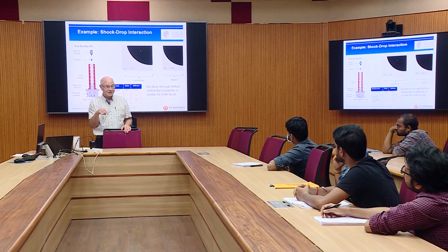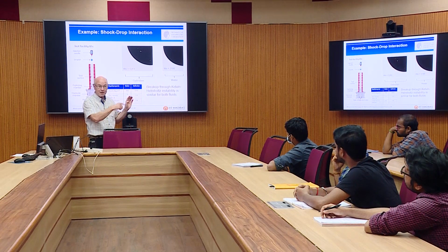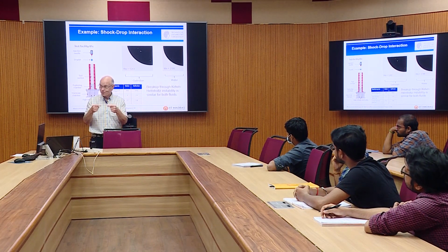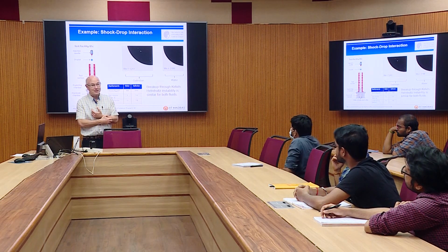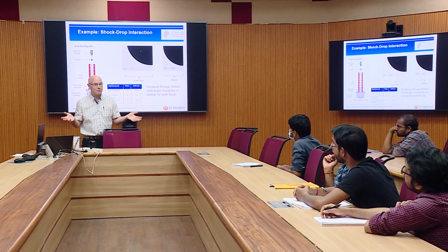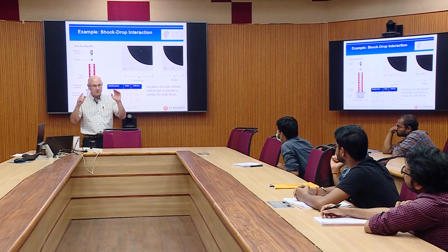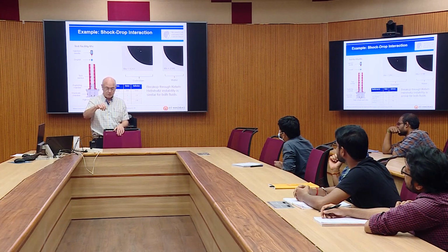Well, you know it's unstable to a certain wavelength, and I showed the dispersion relation, and we know the wavelength where it's most unstable. So we vibrate the hole at exactly that frequency, and then we get exactly that wavelength, and that's what we call a monodispersed droplet generator. That was done by Berglund and Liu back in the 60s, I think. You can buy these things, and they are monodispersed.